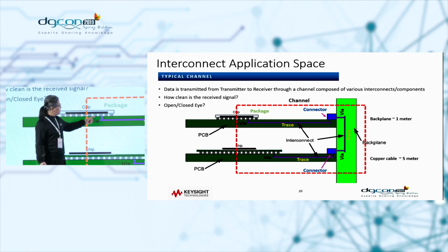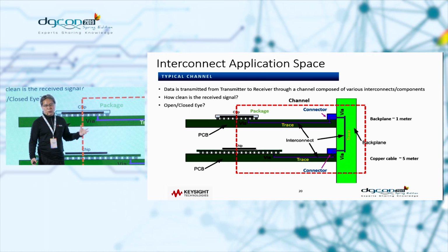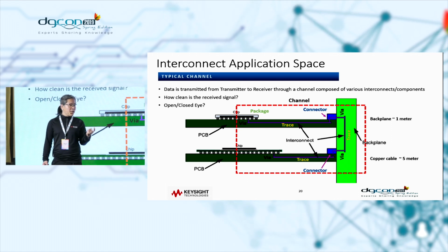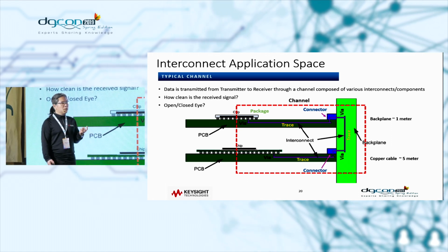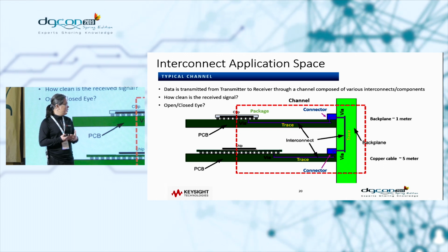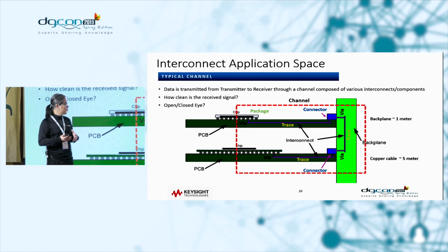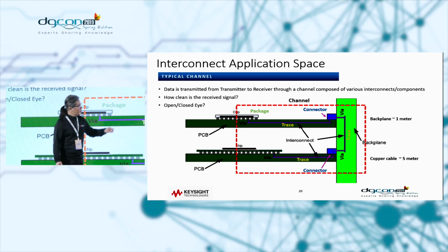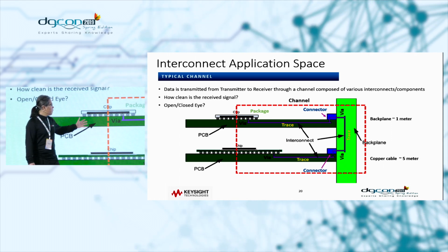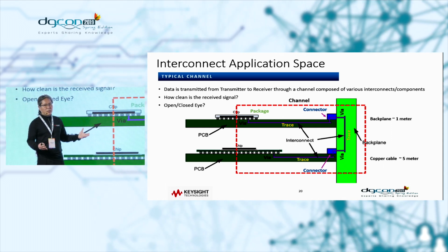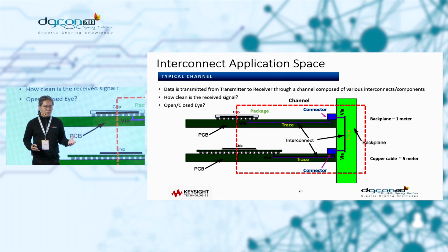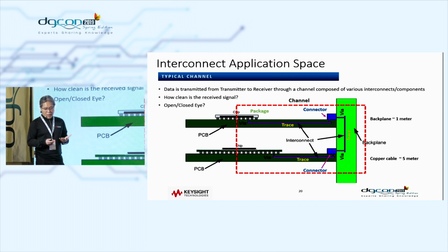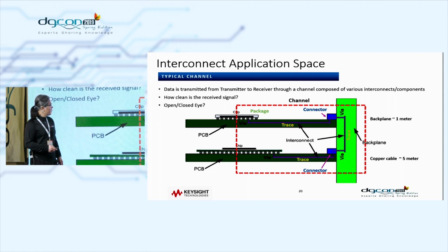But all the problems are coming from the via structures or interconnects. It's because it's very difficult sometimes to define the return path. And there will be unnecessary coupling happening between the differential vias and to the ground planes and so on. So you really need to be able to model all the interconnect properly so that, along with those chip data represented by IBIS AMI, you will be able to simulate it properly and then compare to the measured data with the highest possible accuracy for the design.